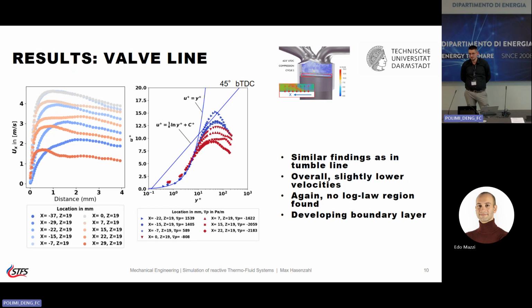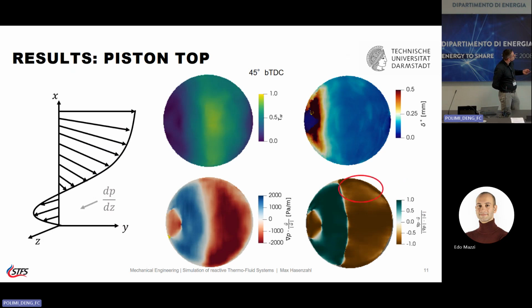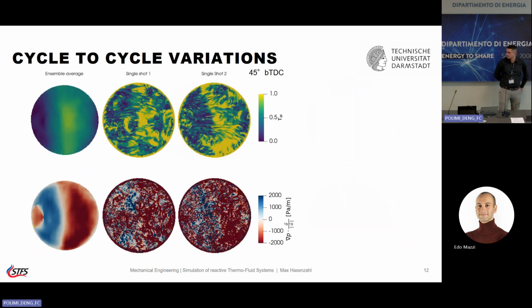And when you look at the RANS data, well, it's not RANS, but if you look at the cycle average data, then it looks all very regular, right? Now think about it, Max, if you can bring up the snapshot of the pressure gradient again from one LES. This is far from being a well-structured thing. As you say, you have a lot of local structures which you need to resolve, impingement, more stagnation point flow, and that might be close to the wall or somewhere else.